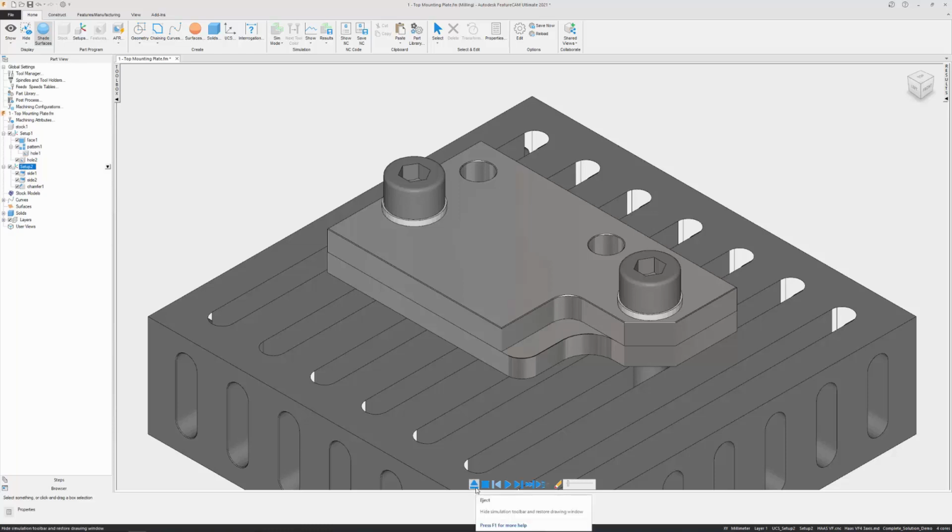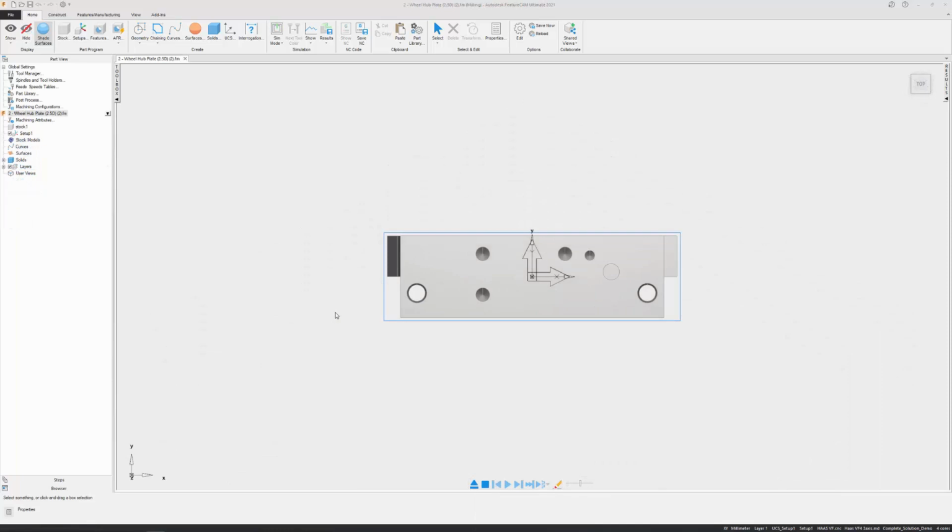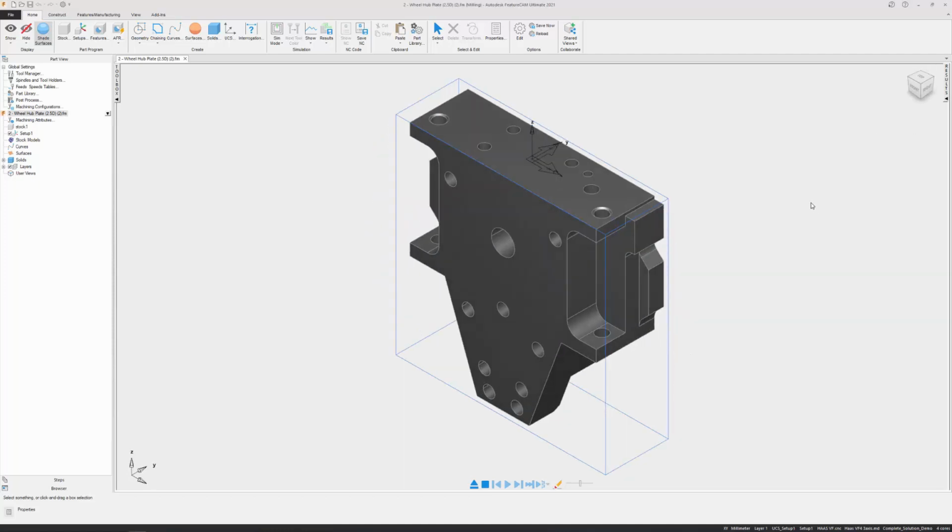ready to start machining. The next component that we'll be manufacturing as a part of our overall steering assembly is this wheel plate hub. Now, we're going to approach this with 2 different operations. This first one, we'll be machining just this top face, a pretty basic setup, just on our 3-axis mill, in our case, our Haas VF4. And we'll be machining this part out of aluminum. We'll then, later on, go to machine the rest of this part on our 5-axis machine using 3+2 machining strategies.